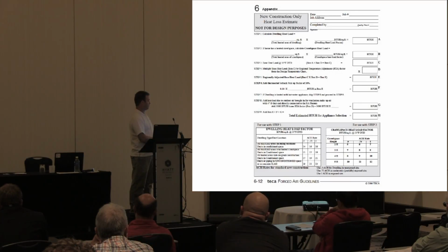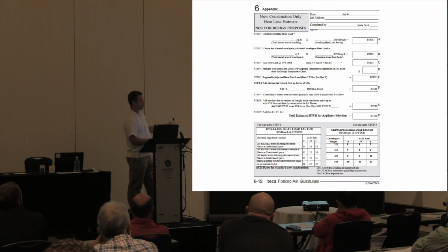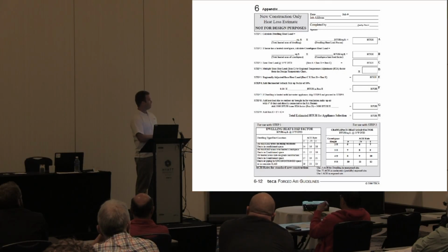So basically, if we're building a basement house in a subdivision, we're using 14 BTUs per square foot. So we put the total square footage up here, we put 14 here. Then if it has a calculation for the crawl space, you can add that in separately. And then we do the base heat loss, so we add them together. We get a total in here. And we multiply the base heat loss by the regional temperature adjustment, which is what I told you. So if it was in Prince George, it's 1.78. So we multiply that by 1.78, and then we get a regional adjustment.